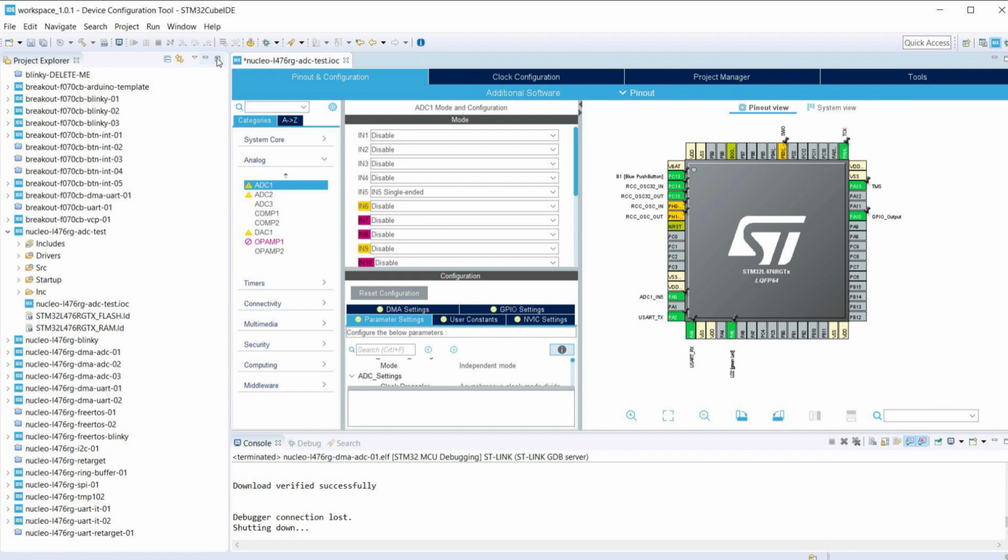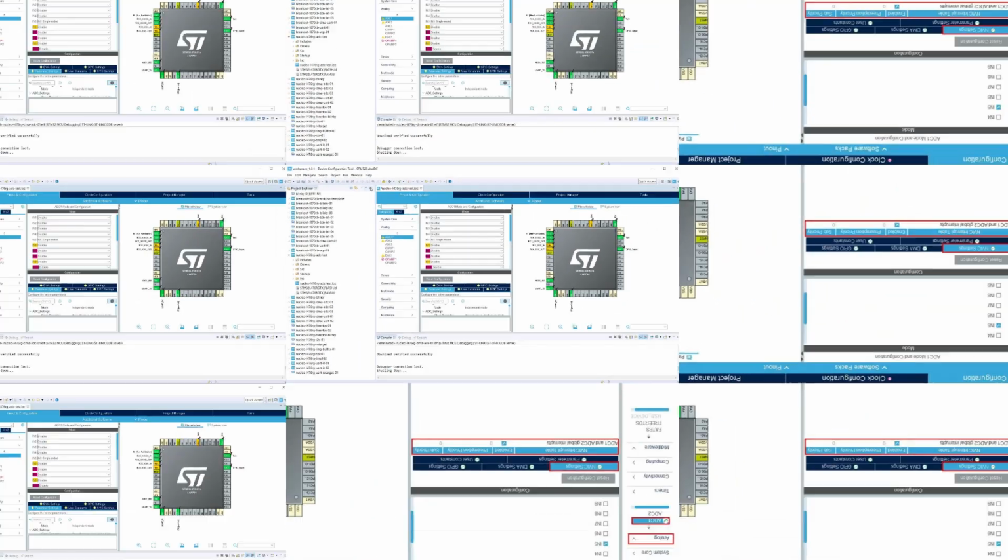Okay, that sounds straightforward enough for maybe one reading here and there, but it also sounds like the CPU is just waiting around doing nothing useful while polling. That's exactly the drawback. In polling mode, the CPU is stuck in that poll for conversion loop, busy waiting. It's burning clock cycles, consuming power, and effectively blocked from doing anything else. Not very efficient. Not at all. Especially if you need to read multiple channels frequently or sample at high rates. The CPU gets completely bogged down just waiting for the ADC.